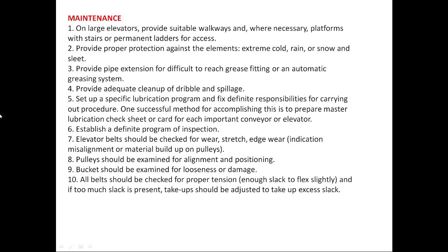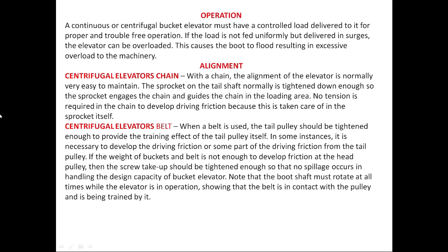Elevator belt should be checked for wear, stretch, edge wear, indication of misalignment or material buildup on pulleys. The pulley should be examined for alignment and positioning. Buckets should be examined for looseness or damage. All belts should be checked for proper tension, enough slack to flex slightly. If too much slack is present, the take-up should be adjusted to take up excess slack.